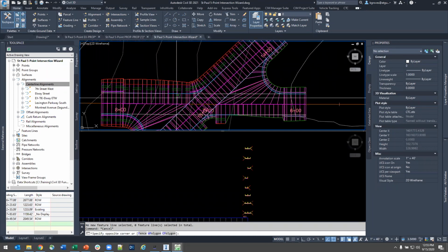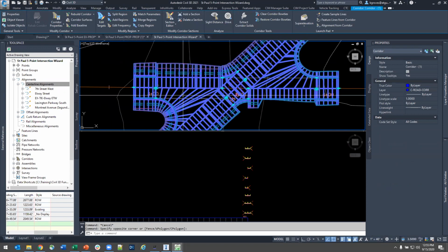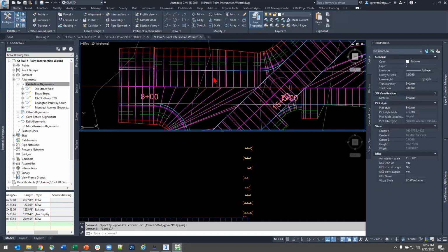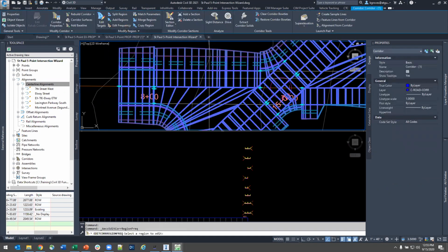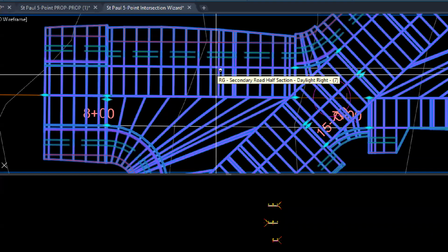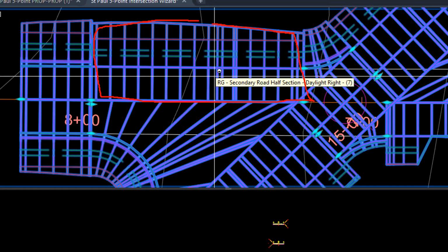The other part here that really frustrates me is that it chooses to define this region right here. This is a half road. It's starting from the center line and it's building to the north as a half road. On the downside over here, this is one of my corridor curb return started feature lines that it's shooting out over that way. I don't see the need for an additional half road based off the center line when we already know that we can make our own connected alignment as long as it needs to be, and it's going to be its own half road that can meet up with our full road later.